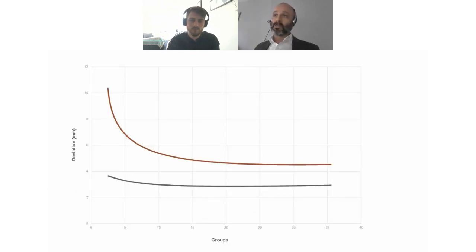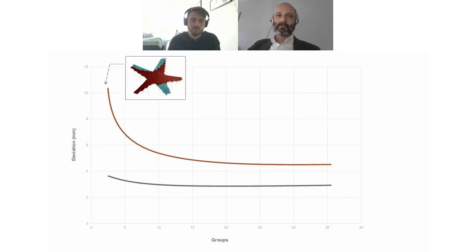So this graph illustrates the results, the top curve being the maximum deviation, and the lower curve being the average deviation, the number of groups on the horizontal axis and the deviation in millimeters along the vertical axis. So for two groups, the maximum deviation was around 11 millimeters, with the average being around 4 millimeters. Considering the manufacturing and erection tolerances might be plus or minus 5 millimeters, and a desire for the minimum gap to be approximately 10 millimeters, in reality, the gap between panels could have been up to 40 millimeters if you only had two groups, therefore quite large and undesirable.